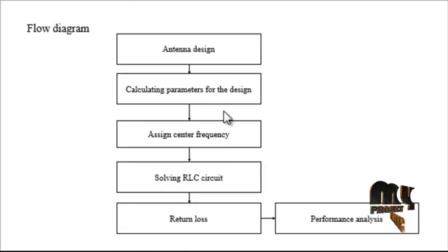The critical parameters of the design are substrate electrical thickness, slot width, probe radius, and feed location variance. There are many other parameters, such as length and width. All the design parameters are calculated in MATLAB, and then the center frequency is assigned.